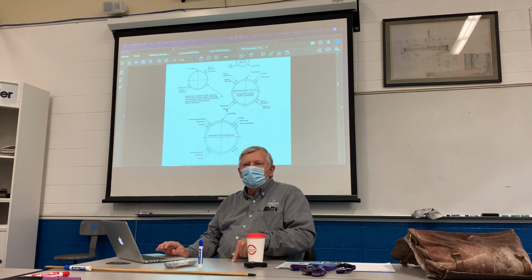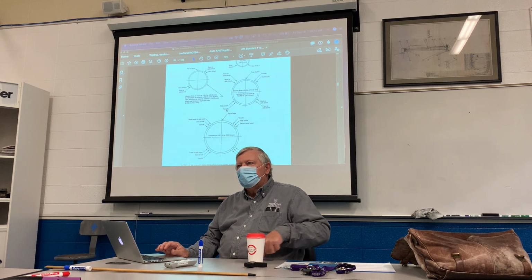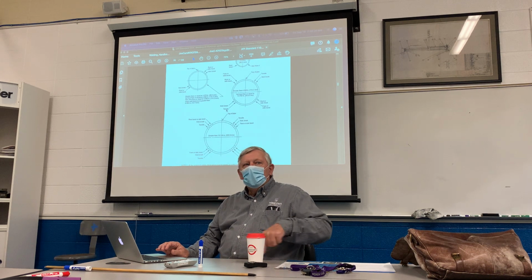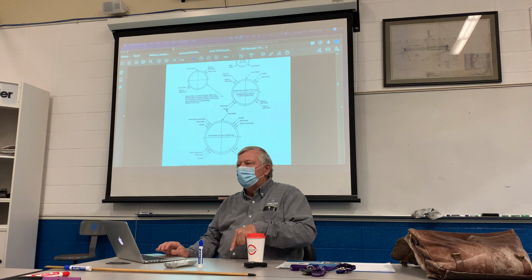And most everybody does nick breaks. Why? Because they're simple, doesn't require a trip to the lab, doesn't require more fees. Now I happen to have a portable high pressure tensile tester. So if we choose to do tensiles, I can do it.